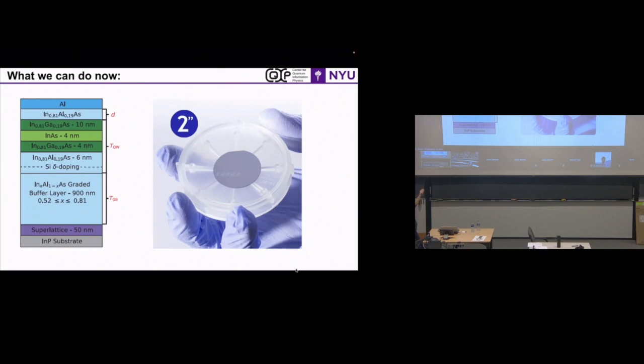And once this comes to the surface, it becomes electrons on the surface, almost like graphene, and then you put the superconductor on top. Indium arsenide by itself is known to have a negative Schottky barrier. If you get regular silicon and put aluminum on it, it moves the electrons away from the surface because it pins in the mid gap, right? So if you draw this band diagram, you have a slope and then the electrons push in. But in indium arsenide, it does the opposite. It brings the electrons to the surface when you put metal.